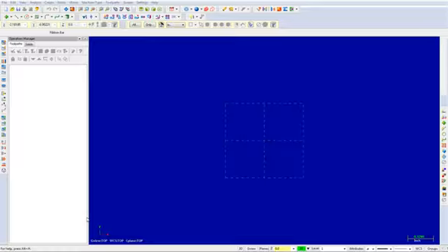You will notice I have not switched my plane to +D +C. For this tutorial, this is acceptable because we make no reference to coordinates. However, when necessary in the following tutorials, make sure that you are in +D +C by selecting Planes, Lathe Diameter, +D +C.